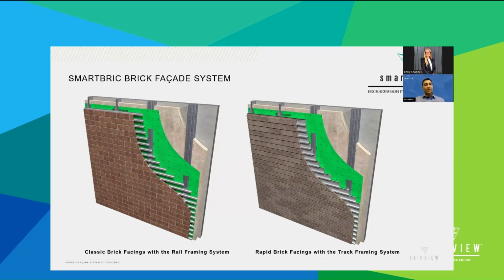The option is for a grouted traditional brick facing or a modern mortarless brick facing, which helps with quicker installation as well. It's a lightweight system, with a weight of just 55 kilos compared to 200 kilos for a traditional masonry brick wall. This brings benefits when installing on a high-rise building, transferring less stress to the building structure, for example. It also offers higher design flexibility, since it can be installed onto any feature in the building and also used to create curved facades.